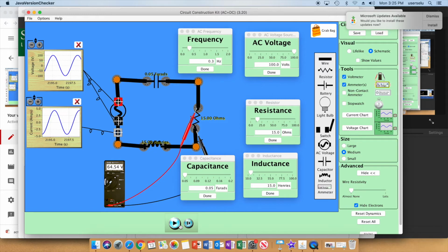You should be able to calculate the peak voltage dropped, and I'm probably not right at the top of the curve, so I'll be asking you on your report to calculate the peak voltage dropped on this and see how it compares to what we were able to measure. Now, I'm also going to measure the voltage change across the inductor. This should be a pretty crazy value, maybe even more voltage than the supply of the system, because the magnetic field of the inductor stores quite a bit of energy and allows it to dump a lot of voltage itself.